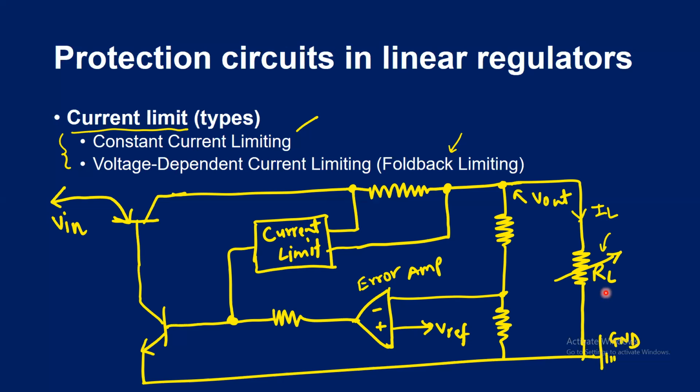We have also seen in our previous module, there are three control loops built in with the modern IC regulators. One is a voltage error amplifier, which is basically used to compare the two voltages at its input terminals, and it senses the output voltage with the help of this voltage divider and compares it with the reference voltage.